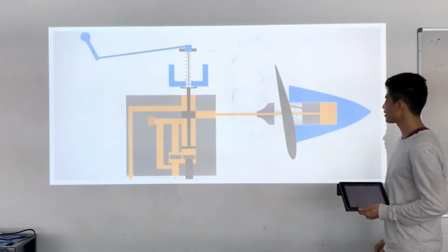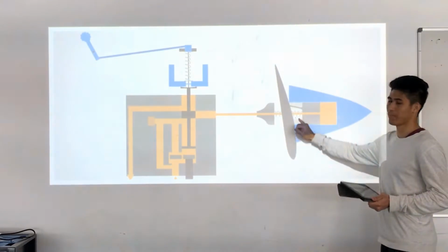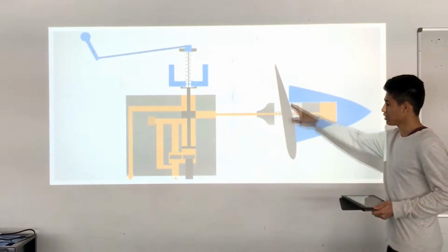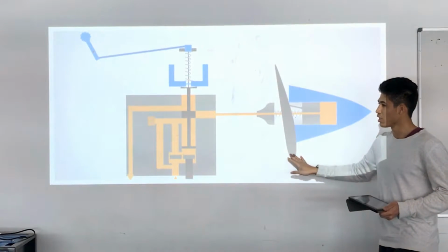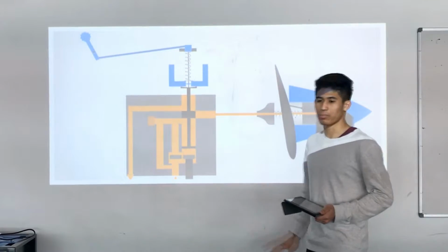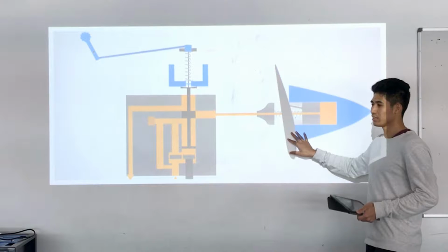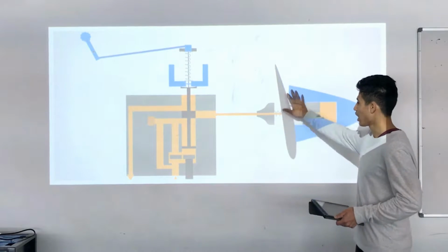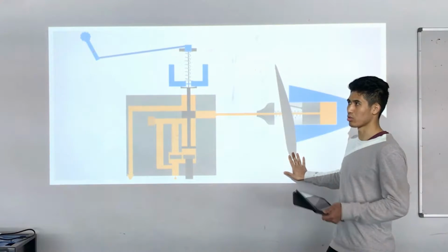This is an example of a variable pitch propeller, which can be adjusted during flight. This is a fine pitch. It is mostly used during high RPM and low speed. So en route on a climb or a descent, when the propeller has to rotate at a high RPM, the pilot in command will fine the propeller to a fine pitch, allowing the propeller not to overspeed and to fly at a slow speed.